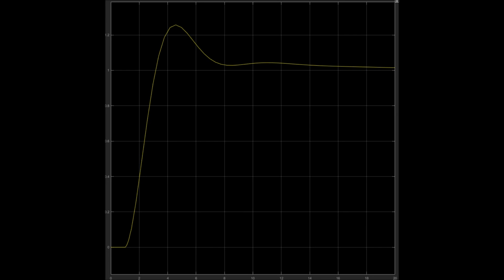However, we did find that the overshoot and disturbance were mutually exclusive with response time, so we could only choose one or the other, and we figured that it'd be best to have both of those addressed and then just have a longer response time, because in the end, for practical purposes, one would want to have their package delivered intact rather than have it delivered fast but broken. So our group recommends utilizing the PID with the parameters set for overshoot and disturbance rejection.